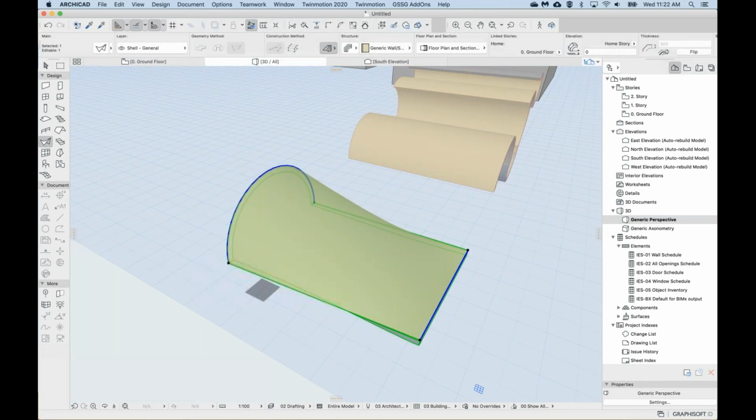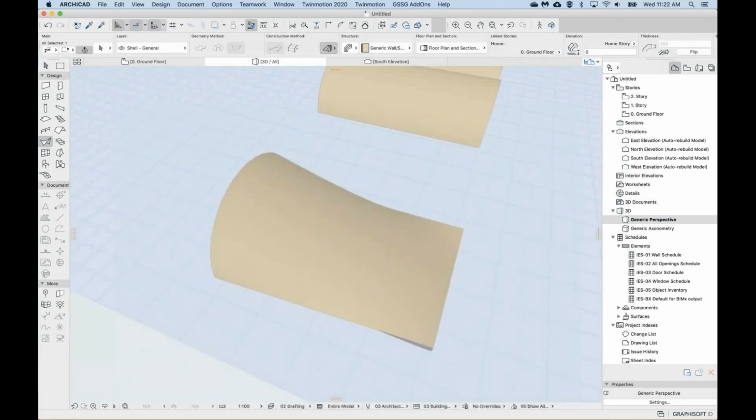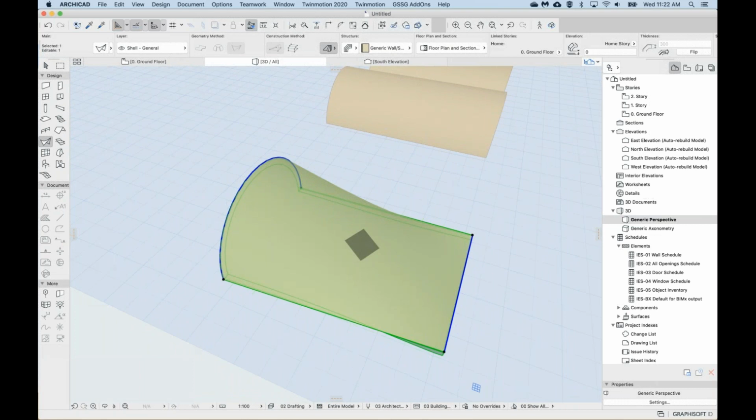Okay, so let me know if you can get some shape like this, where the two profiles are more or less parallel. Or if you need me to show, got it, great. So again, this is more complex because we have two profiles, and each profile we can actually continue just like how we did for the extruded method or the revolved method. So each profile I can edit and control.